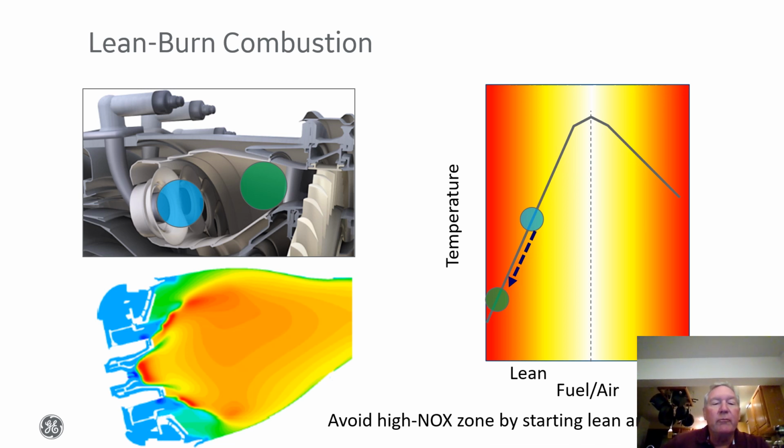And that's where we, rather than having these dilution jets come in to dilute and further react a rich primary zone, actually bring most of the air through the front end of the combustion chamber, mix it with fuel prior to the flame front, and then burn in a fuel lean mode, both in the front region of the combustion chamber and maintain that lean burn condition all the way through.